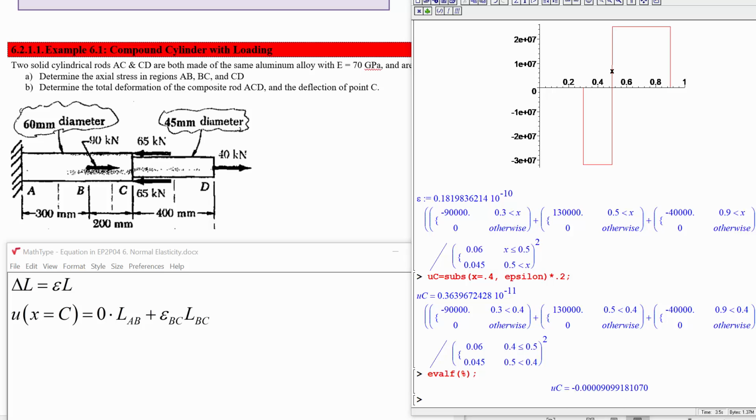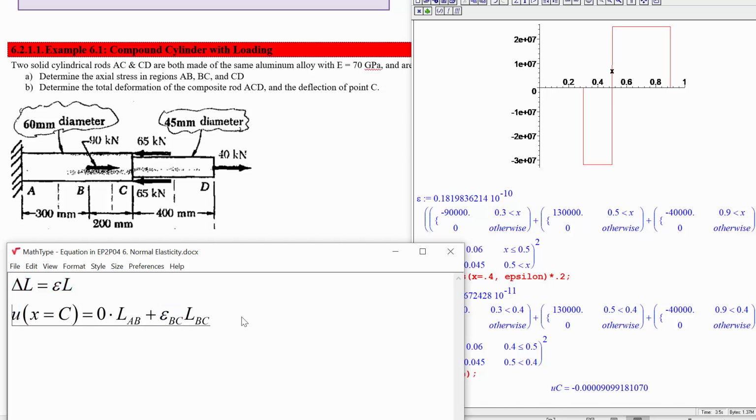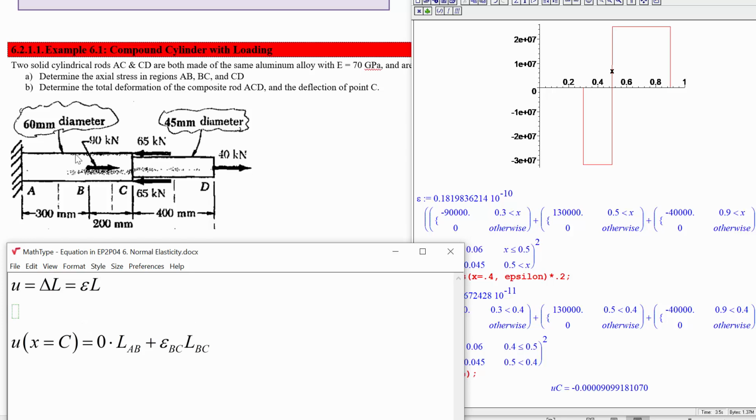Now, I know what you're thinking. You're thinking, Dr. Minnick, isn't there a way that we could do this with integrals? And you're right, absolutely. So, why have this macroscopic thing here when you could revert this to saying, you know what, this total displacement, this u that we've gotten, the displacement when we have the left end fixed, is just the strain times the total length change that we're talking about. So in a differential sense, for a little tiny piece of it, the little bit of extra displacement that piece has gone must be equal to epsilon times the little bit of x displacement that we have.